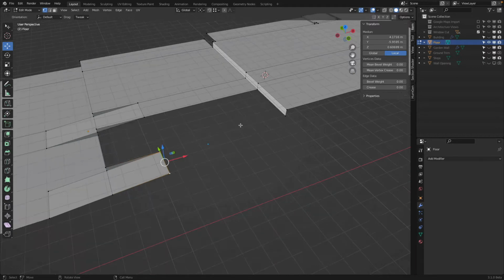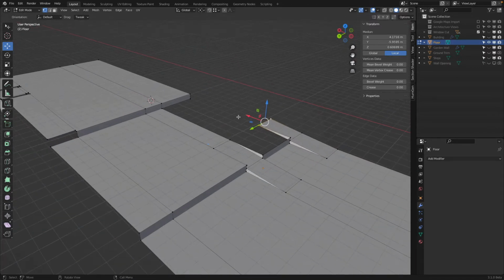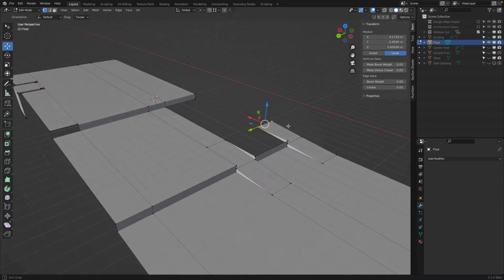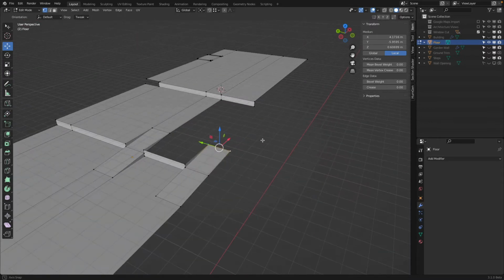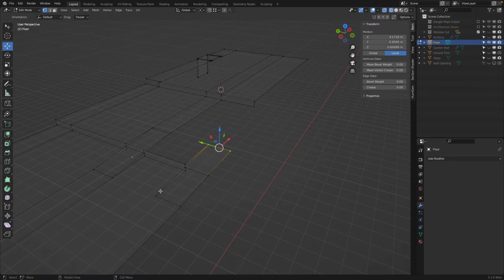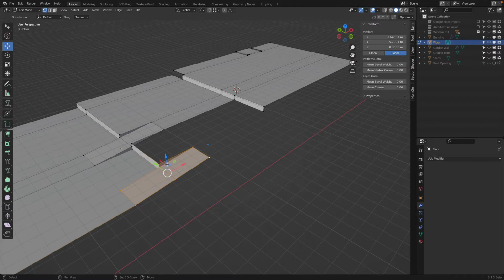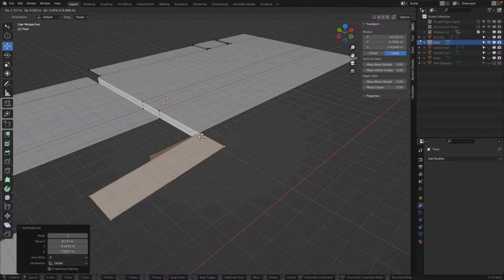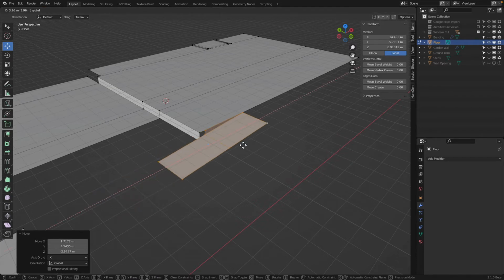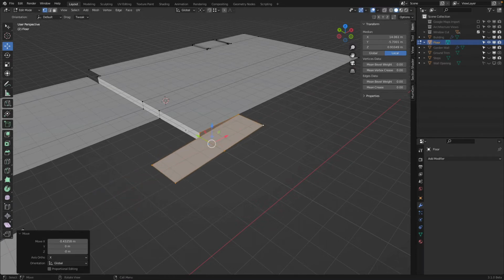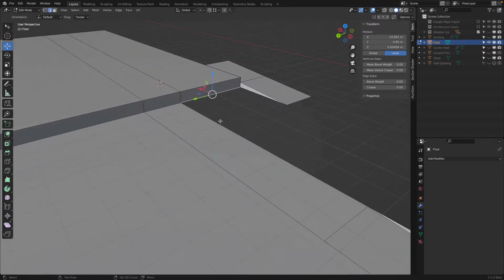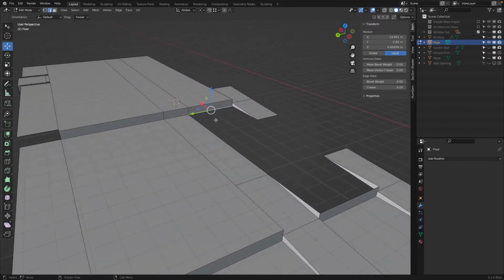There will be another ramp coming in. So how can we maybe copy this ramp in there? Let's see. Z and wireframe. With B, I select all this. Shift D, make a copy, move this around. G, yeah, okay, get this maybe closer. G, yep, then it worked out. Very good. I select this edge here and say,